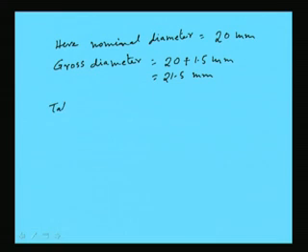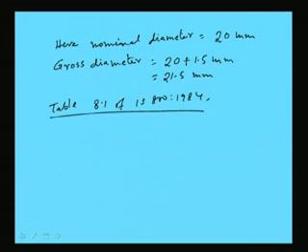That means, the dimension due to clearance will be taken extra as 2 mm. And if the nominal diameter of the rivet is less than 25 mm, then the additional dimension will be added as 1.5 mm. So, here it will be 1.5 mm. So, from table 8.1 of IS 800 1984, we can find out the shear stress.